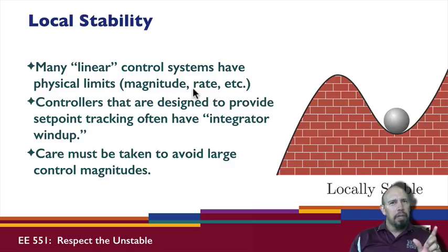If you look, for example, at a resistor, V equals IR, that relationship holds very well until the smoke comes out, right? Once the smoke comes out, that little thing no longer has the same resistance that it did before the smoke, while the smoke was still in. And so the systems are not linear. If you exceed the power rating or the wattage, then the system will generally not behave like it did before you violated that. So the system's not linear.